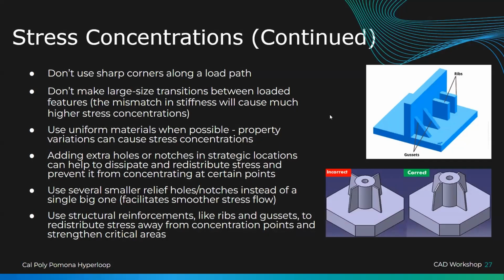So to continue, don't use sharp corners along the load path. Right here, you can see that's a chamfer. A fillet would be if it was just a smooth curve. But you can see a sharp corner versus a chamfer, this is the better design.